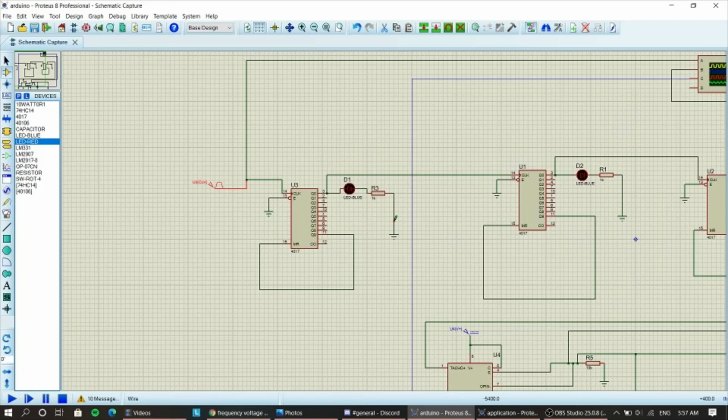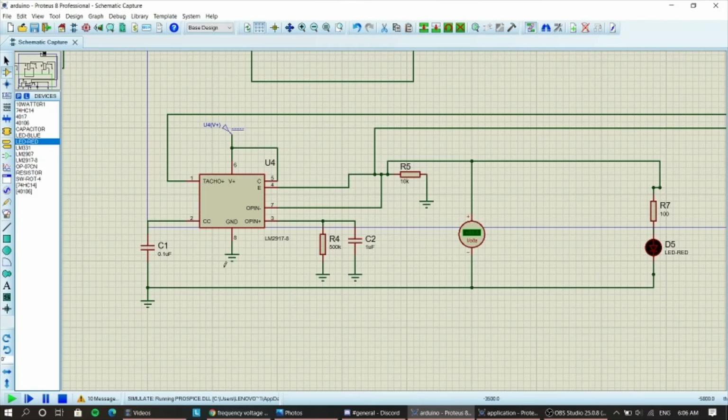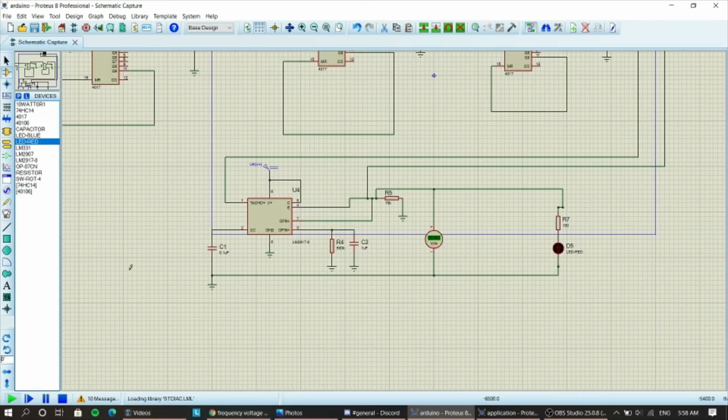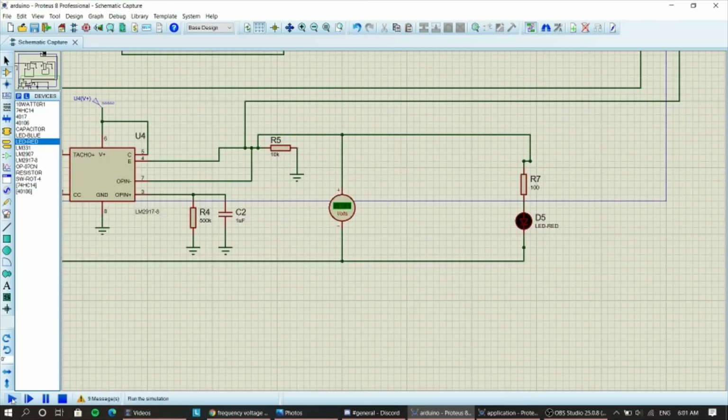So next, the second part, where the output of the receive frequency goes into the converter, and the converter will convert the frequency into voltage. So we check for the first input, where the input is 225 kHz, the maximum output is 1.54 volt and the LED is the dimmest. And then the second is 240 kHz. The maximum output that we can get is 4.54 volt, and the LED is brighter than before.